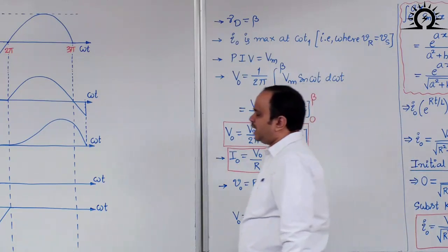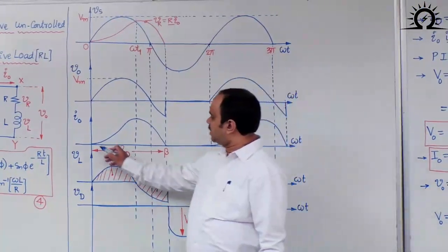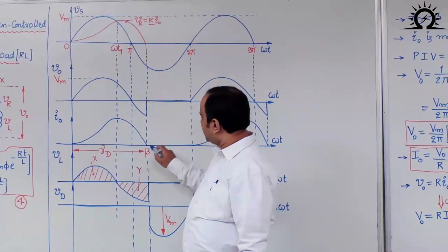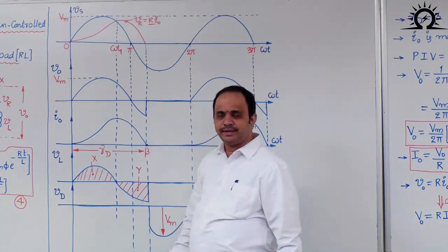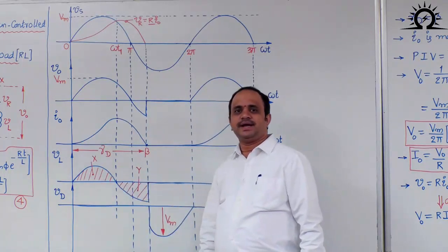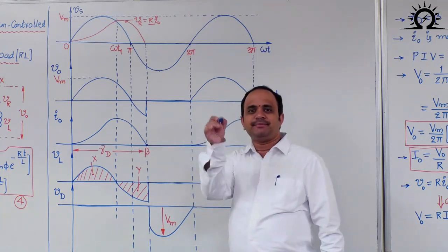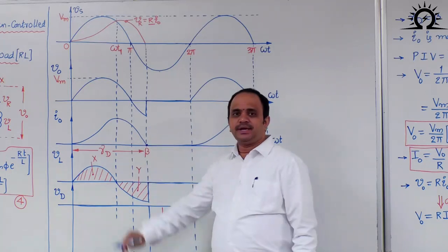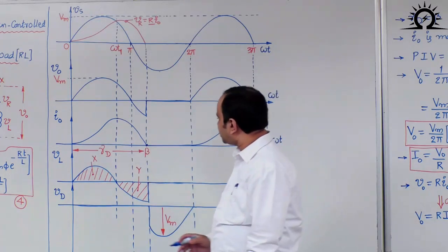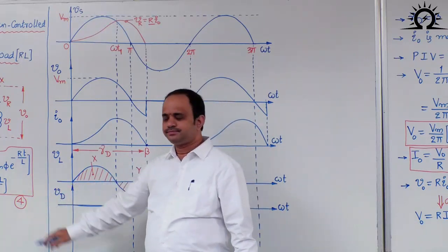Next, another important point. We discussed beta in the output current waveform by using the volt second balance idea. But I want to get the beta value exactly as some number. What should I do? I have the I naught equation, which is equation number 4.